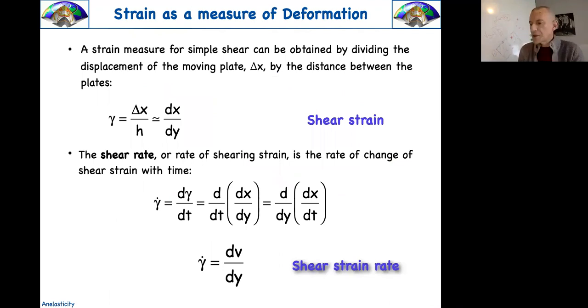So just developing this idea here, if you imagine now to measure a shear, a shear strain, you imagine the delta x with which you're pulling your fluid, you consider the height of the fluid, and you consider the strain inside the fluid. So you take this, and if you compute the shear rate, and now that's the key, this dot here is the key. If you compute the time derivative of this quantity here, you get something that is telling you that the shear strain rate in a viscous fluid is decided by the slope of velocity.